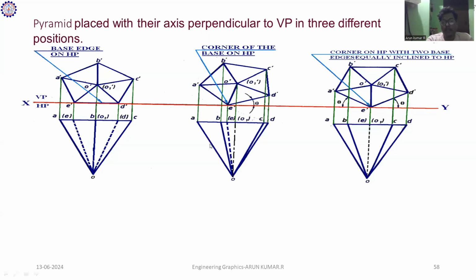So then we construct the front view and complete the top view. Next step, we give the names for that diagram. Clearly, A, B, C, D is the base of the pyramid and O is the apex or vertex. All the corners joining at one point, that name is called the apex or vertex, which we mention as O. Then we proceed to representing the dimensions.